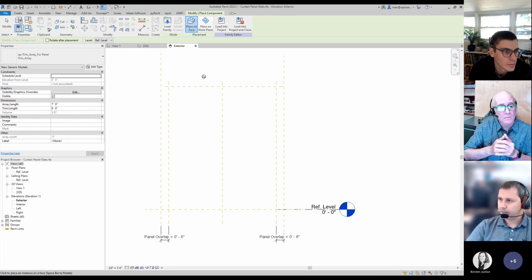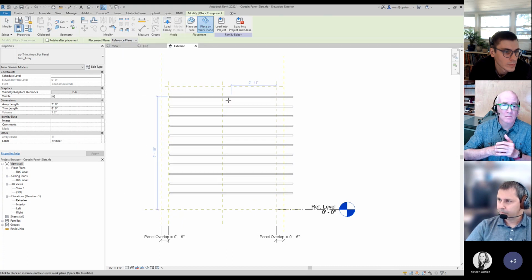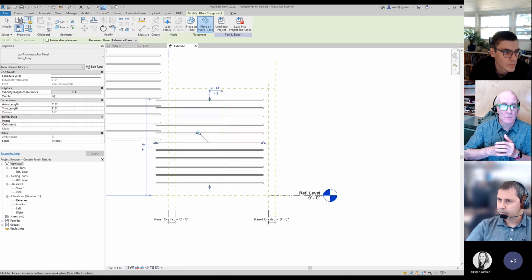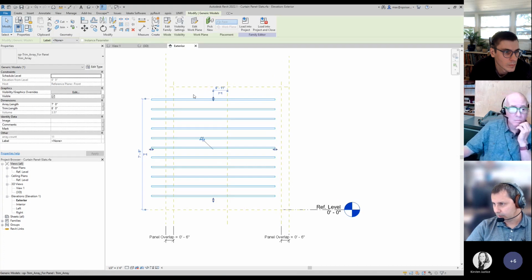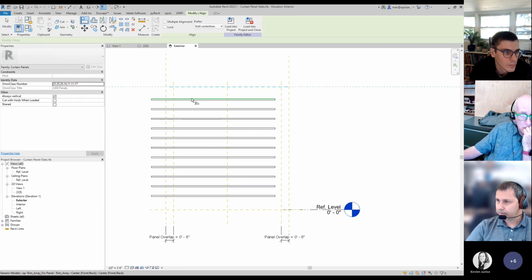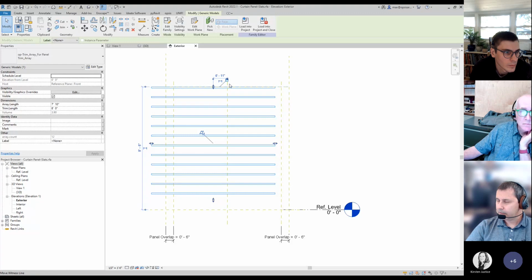These are components. So this has an X through it, but I'm going to place it on a work plane, which is basically the front of the curtain panel. If you remember from last week, the way we lock this to the family itself, actually, I'll just use the drag points. So you want to lock the panel to these edges.